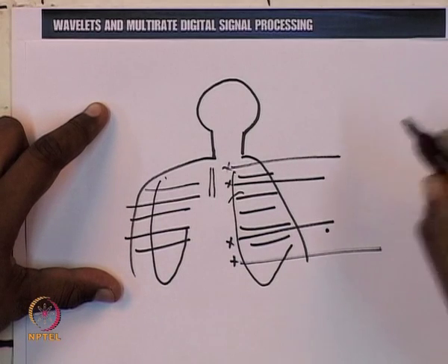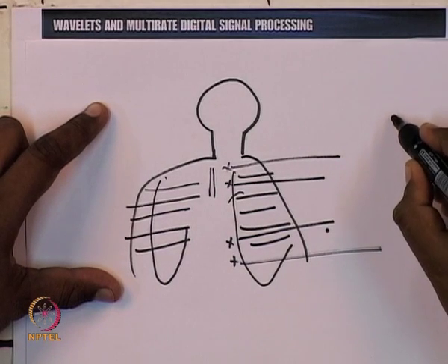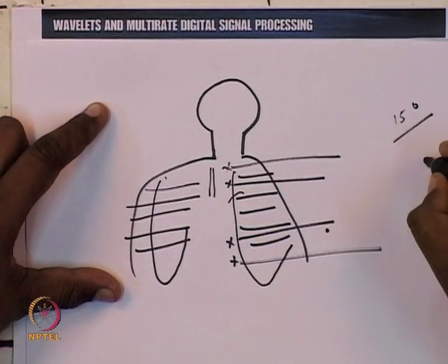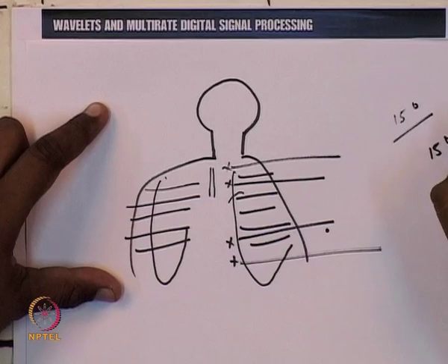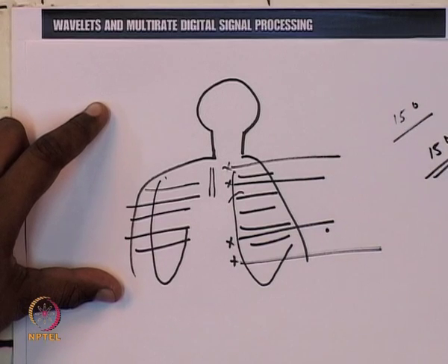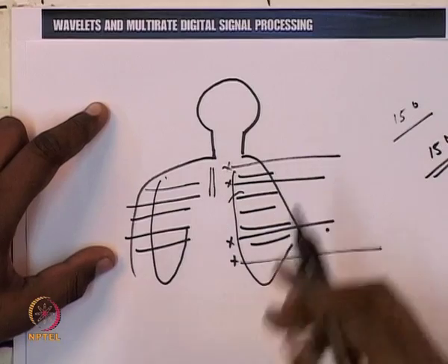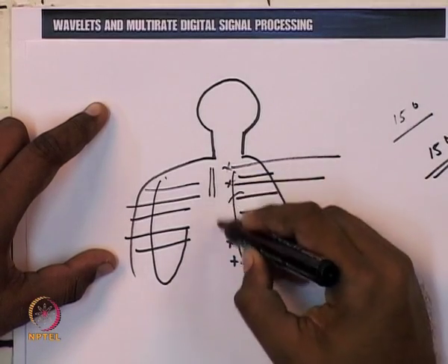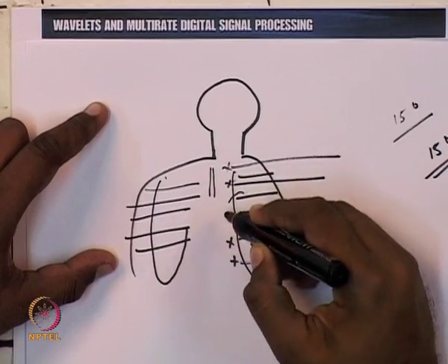If, for example, the conductivity of blood is 150, then the conductivity of lungs and other muscles is 1500, or 10 times lower compared to blood. So whenever the heart is pumping, what will be happening? This aorta will be changing its dimension. Because of that, the voltage we are measuring changes, and we can find out the impedance variation from that.